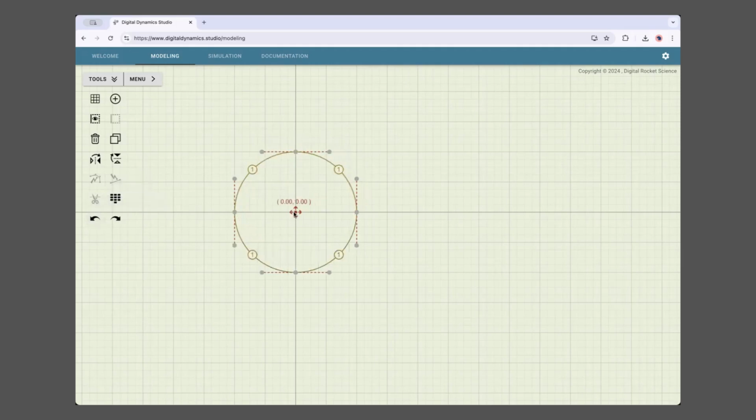And so that works with basically anything. You can do the angle. If I select this guide and do numerics, I can set the angle to, let's say, 33.3 degrees, and then I get exactly that angle. And points, of course. So you can select a point, numerically set its value, let's say -1, 2. You can exactly set a coordinate of anything. And the hotkey is just the N key on the keyboard. So if you type N, that same tool comes up and you can set exactly the value that you want. So this is a very useful tool, the numerical icon or the N hotkey.